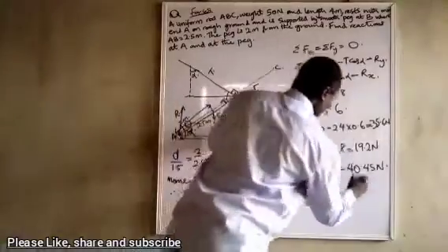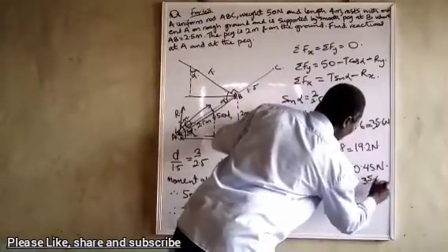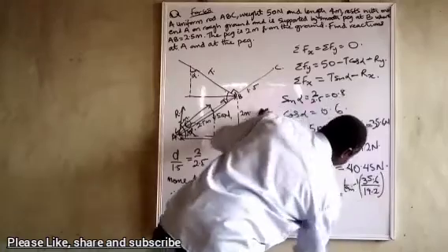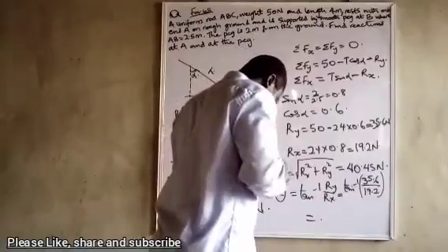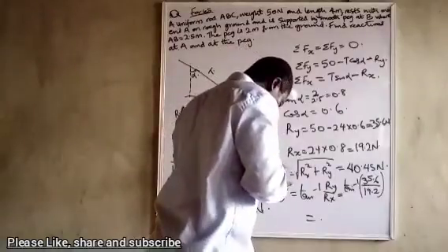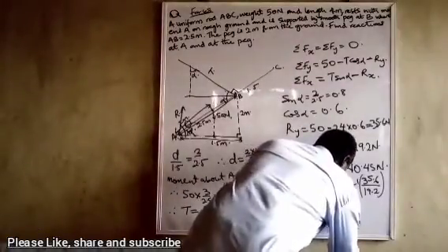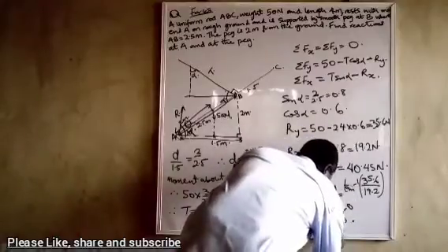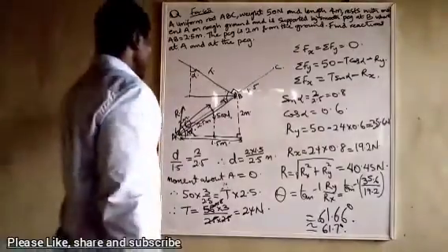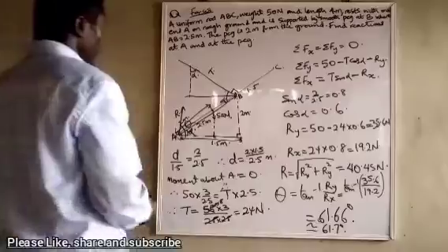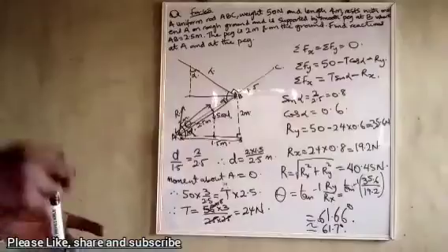And that will give me arctan 35.6 divided by 19.2. And that's giving me 61.66 degrees, approximately 61.7 degrees. So you can go through any means and you get your answer. You can even draw your triangle because the forces will be equal and you will get it. Since you have known this angle, you have known this one to be perpendicular to this. So you get everything right.